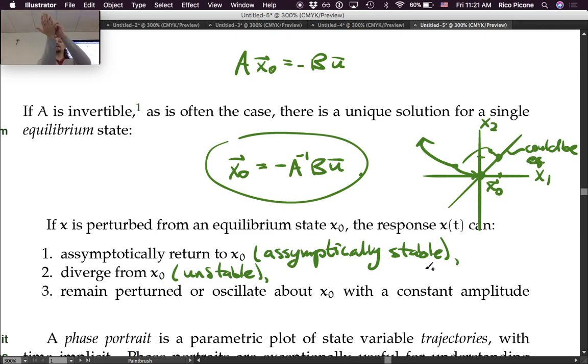In equilibrium, if this thing's just perfectly straight up, and you were perfectly still, and the air wasn't moving, that's an equilibrium point, right? As long as nothing disturbs it, it's not going to move, it'll just stay vertical. But if it gets perturbed at all, like a little wind gust goes by, or you sway a little bit, that thing's going to start to fall, right? And unless you actively try to balance it, it's going to fall. So that's an unstable system. That's an unstable equilibrium point, that vertical point.